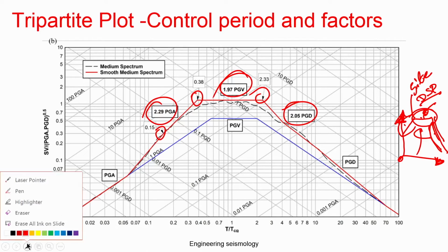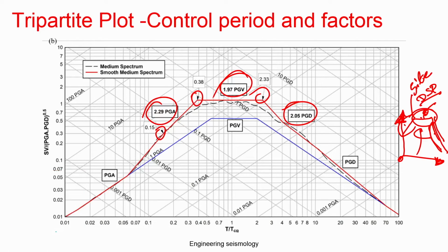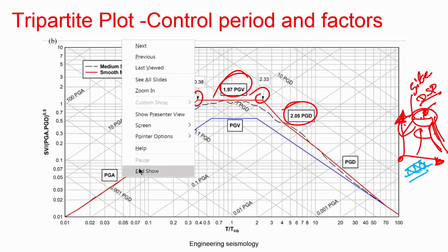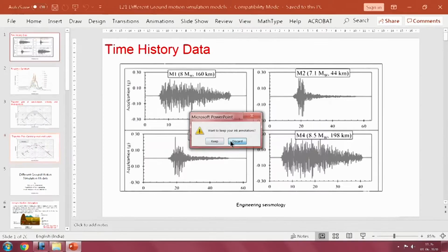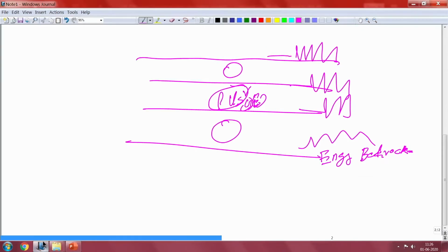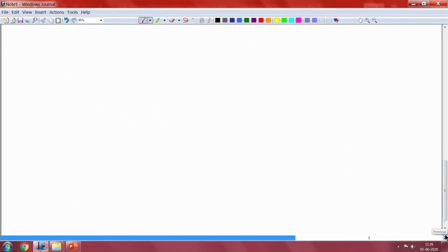So, as of now our code design spectra need to be updated after proper research and understanding. The soil spectrum at acceleration-sensitive, velocity-sensitive and displacement-sensitive regions is completely different. As I said, the western codes are updated versions, so I will give you a glimpse of how that spectrum looks, by drawing how ours and their western country code actually look.